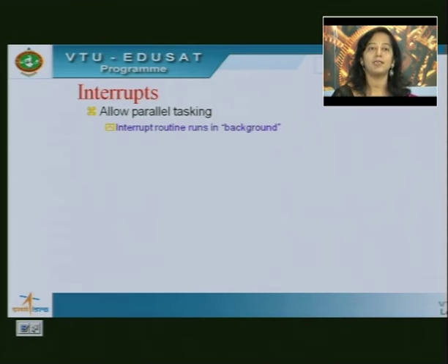Say I got interrupt 0, then interrupt 0 requires me to read in some data which has come from an input unit. So to read in that data, I would have written some code in some parts of the memory. So what does this 8051 do? It goes to that memory, it reads whatever code is there, it executes that code. That code is to read in the data, and once that job is done, it will come back to where